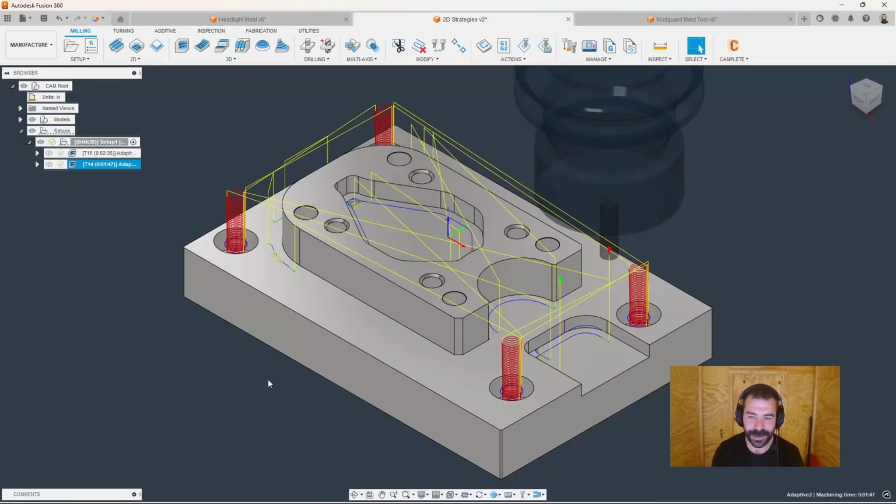All right, looking at our part here, we can see our first scenario. How often has this happened to you guys where you went ahead and did some rest machining? In this case, we're using a 1/4-inch end mill after a 1/2-inch end mill, and we're boring down into those counter bores, yet we don't want to currently with our roughing strategy. Again, this is at a simple level of how we can utilize a couple of different strategies, utilizing the model section of our toolpath to fix it.